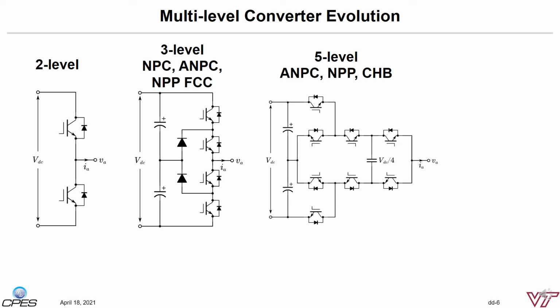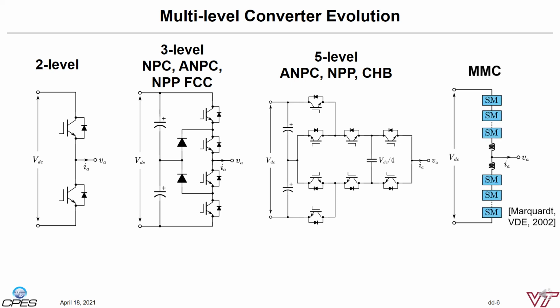These topologies were dominating the medium voltage space for years. Therefore, the straightforward way for reaching even higher voltage is to try 7-level, but the commutation loops are extremely complex, as well as the modulation methods. In 2002, the MMC converter came along, which presents a completely different design concept. MMC is a 100% modular-based approach, and people just need to stack up identical modules to reach high voltage.